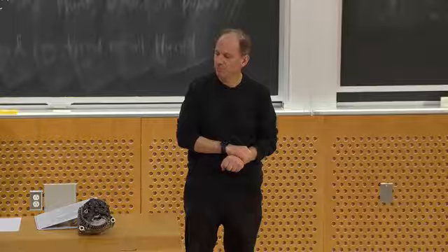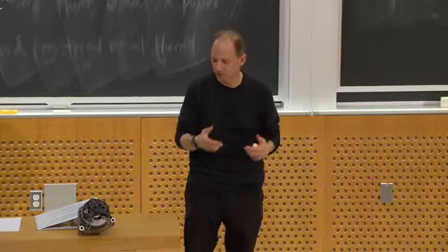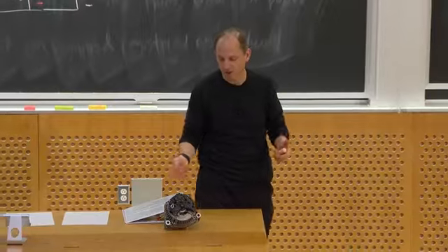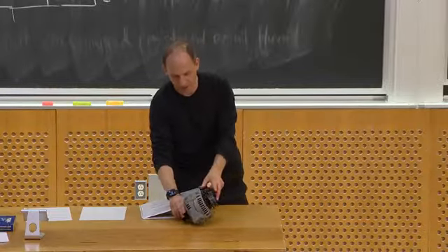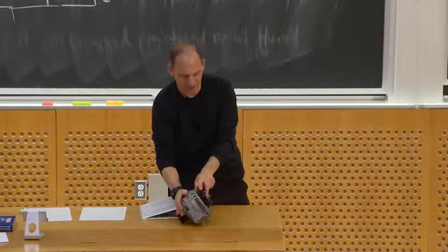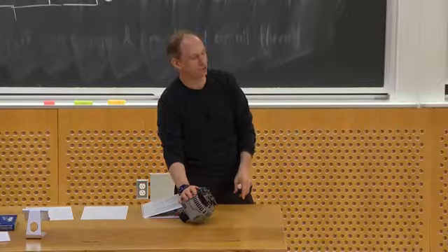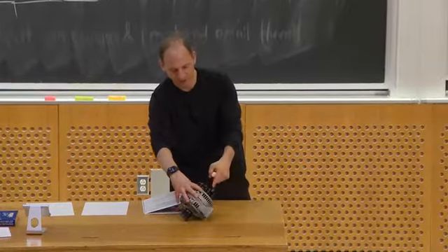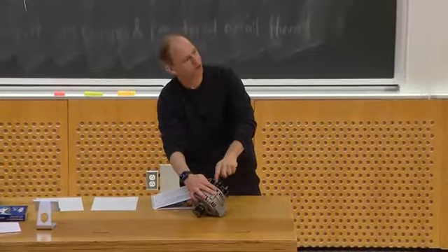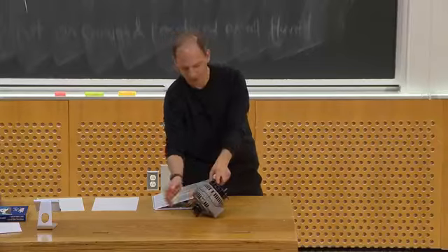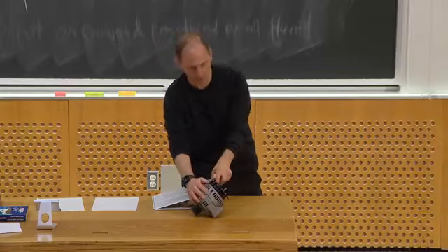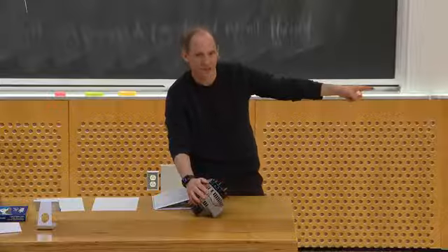The last example where I'll show you where this kind of thing turns up is in any kind of generator. So this is an automotive alternator. What it does is it has an electromagnet that essentially spins inside a set of coils, generates a big voltage. And then there's a set of rectifiers. These are the diodes right here. They turn that AC back into DC.